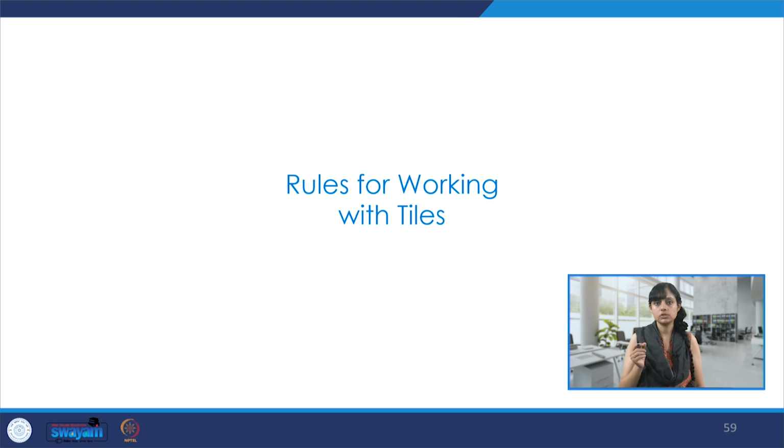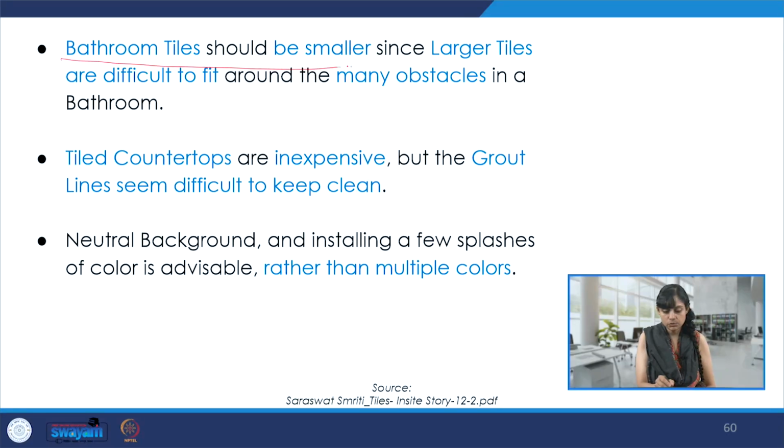Now, what are some rules for working with tiles? So, bathroom tiles should be smaller, as a thumb rule, since larger tiles are difficult to fit around the many obstacles that one could find within a bathroom space. Then the tile countertops are inexpensive, but the grout lines may be difficult to keep clean. So if we are using tiles for countertops, then there is this issue of maintaining the grouting. A neutral background and installing a few splashes of color is quite advisable rather than using too many colors all at once.